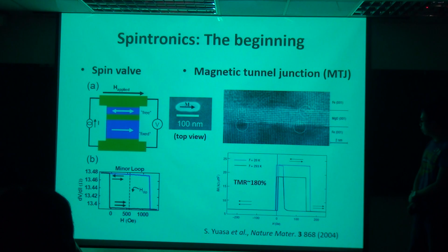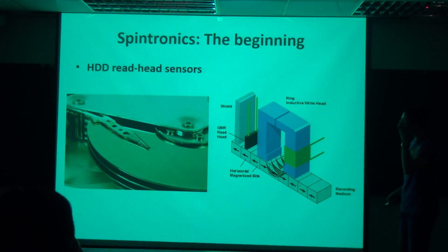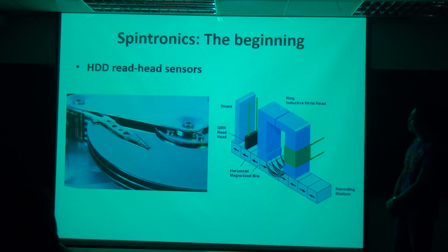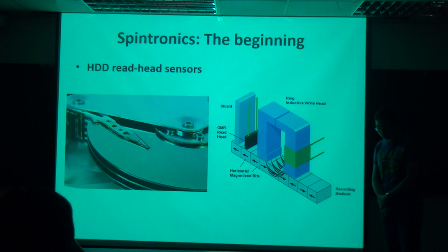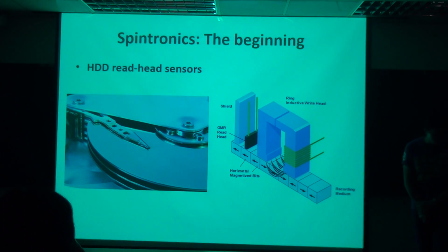And that's the reason why you can see the possibility of building real-world devices out of this kind of tunnel junction. And actually, that's the standard material system for all the MRAM devices that you see from major companies. Later, I'll show these company names. But anyway, due to the discovery of GMR and also TMR, we typically would say we improved the capability of the hard disk drive due to the read head sensor, because now we can use GMR or TMR to do the readout, so the signal to noise ratio is much better than before. But that's just one thing.